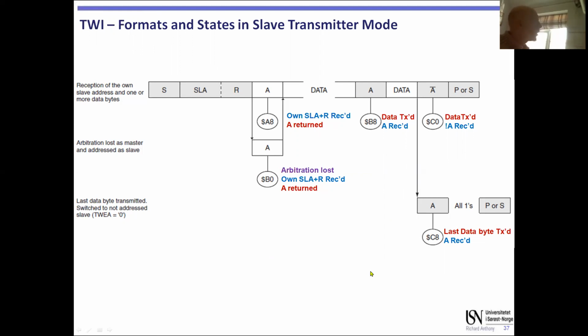But you can see just by these couple of slides that the state machine of what goes on in this protocol is complex, and you wouldn't use this as a first choice if you could just use a UART, for example. In fact, if anything, this reinforces how useful the UART is, because it's so simple compared with this. But if you want to do something interesting and complex where you have multiple devices effectively networking, then you need this and not the UART.